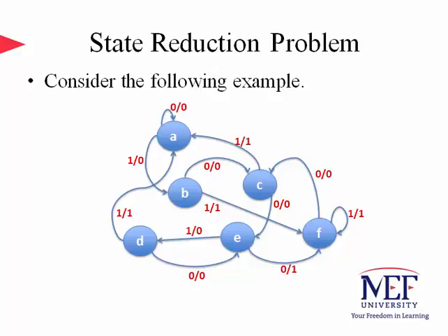The state diagram shown in this slide is a directed graph showing the relationship between the states of the system. Let us assume we have 6 states labeled using the first 6 letters of the alphabet, A, B, C, D, E, and F. The arrows show the transitions from each state based on the provided input and the resultant output bits, so that there are 2 outgoing arrows for each state, one for the input 0 and the other for input 1. You can realize that the graph is connected and you can traverse all the states provided that the appropriate input is fed into the circuit.